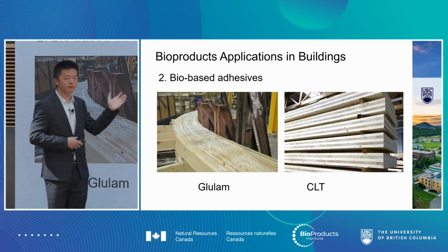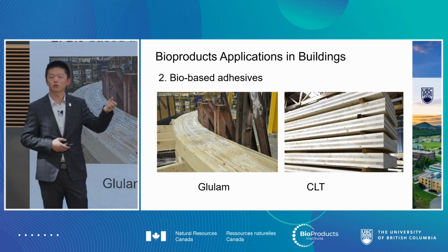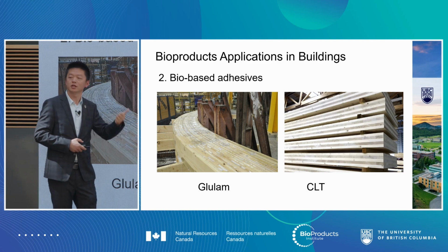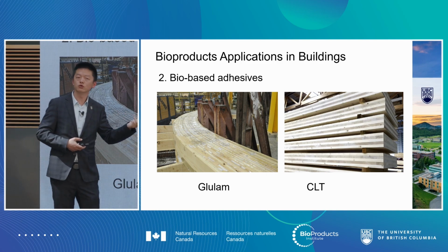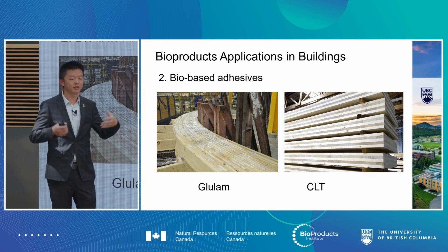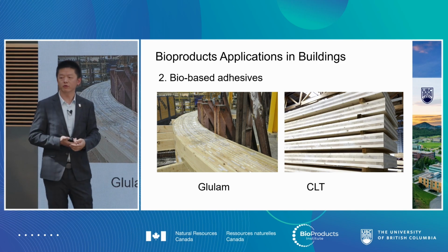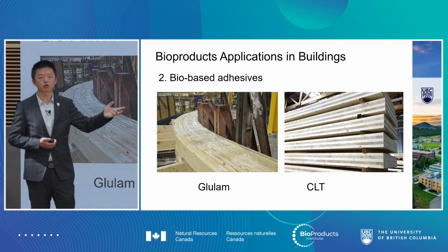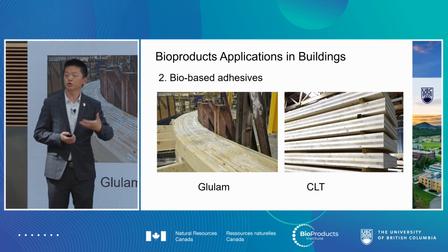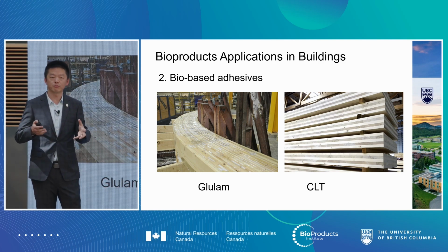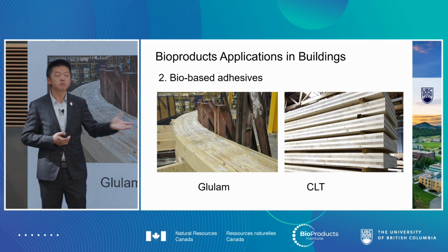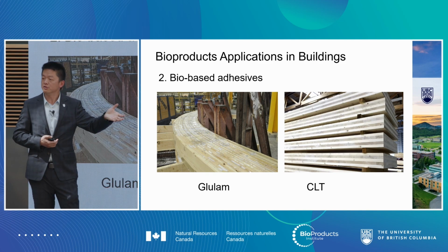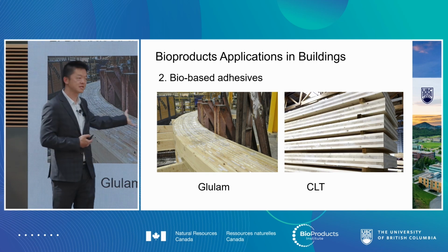And for mass timber, you might have heard of it. What are mass timber materials, right? CLT, glulam, even plywood, all these are heavyweight timber. For glulam and CLT, we have a course in wood science asking students to analyze the carbon emissions of mass timber manufacturing. It turns out the glues or adhesives are the major carbon emissions or environmental impact of mass timber.